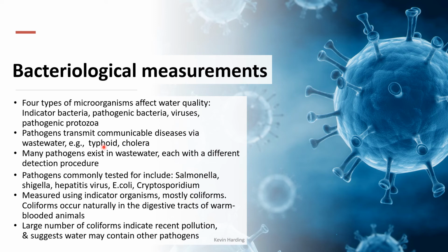So poor water quality and high levels of pathogens can cause illness in humans that are near that or that drink that. Many of these exist already in wastewater, and there are various different detection procedures that can happen. Commonly, though, we test for an individual pathogen. The most common is often E. coli. So if you have E. coli in the water, it can be an indicator that you have other pathogens, so not just the salmonella and these listed here, but other pathogens which can be dangerous to humans.